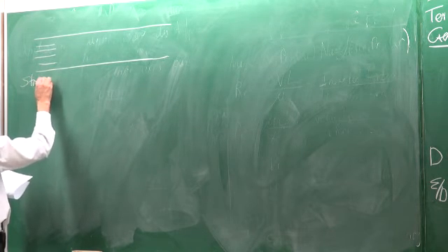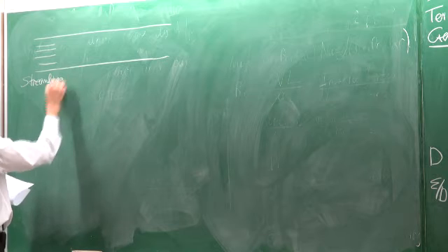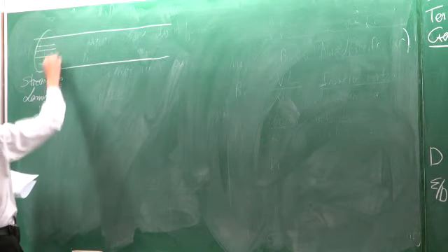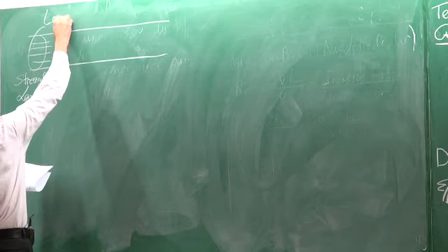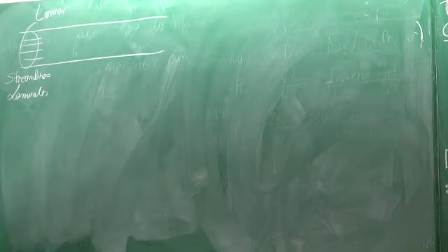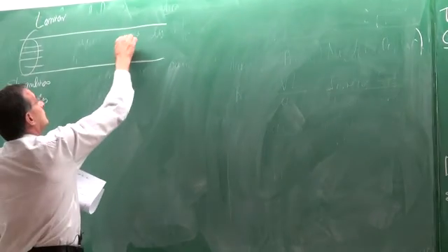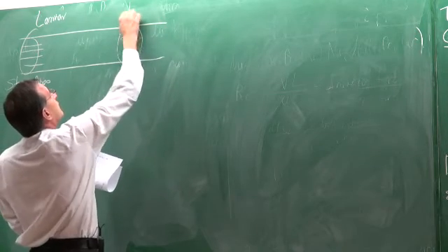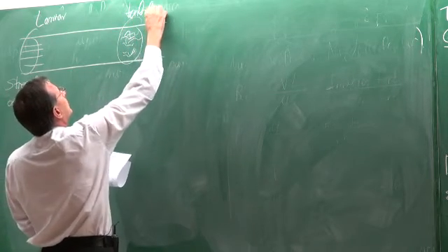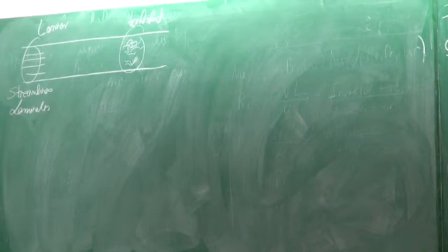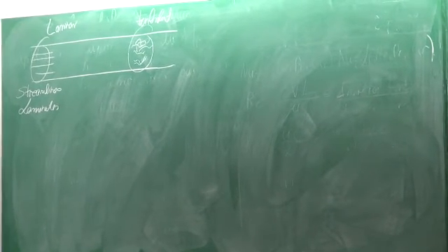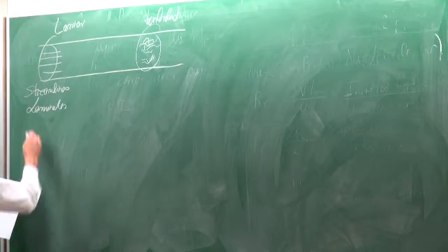That's where the word comes from. So streamlines or laminates, then the flow will be called laminar flow. Okay. However, if the flow is more chaotic like that, then the flow is turbulent. And we've got transition in between the two, which is quite a complicated velocity regime.